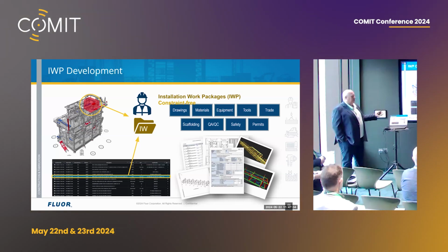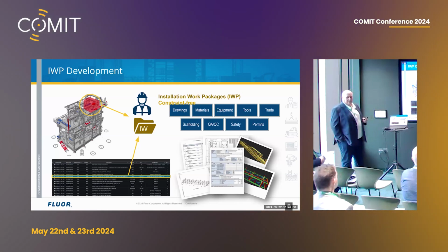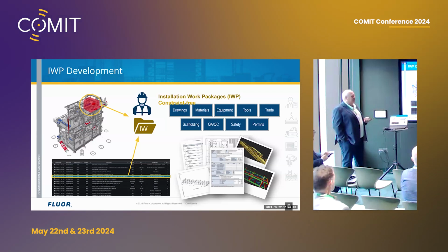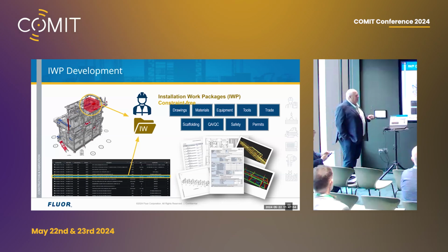We say it could just be like the scaffolding, but we actually go down to, have you got the right PPE for this? Is there any specialist chemicals you're handling? Have you been trained in the tools? It's okay putting it down, but if your workers aren't competent, we don't want to put them at risk. Have you got the permit to be there? All that needs to be identified before we actually start work.